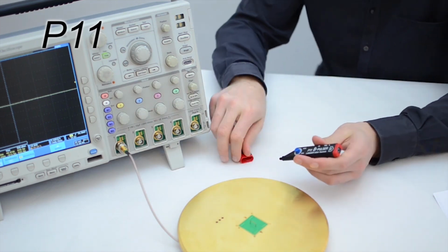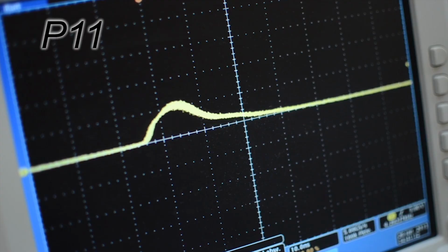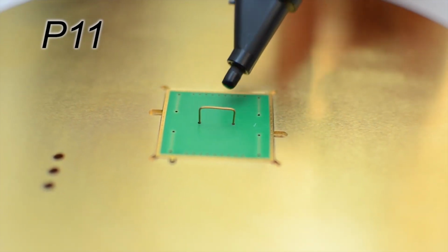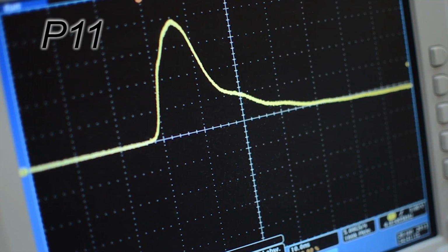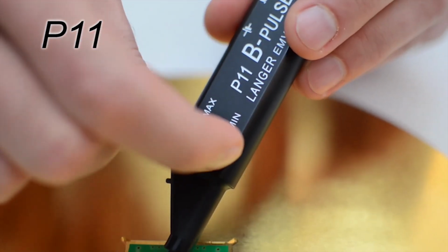The disturbance pulse is triggered by pressing the Start push button, and we then move the mini-burst generator towards the electronics. This is what the voltage induced by the mini-burst generator looks like. It has a width of approximately 5 nanoseconds and an intensity of 15 volt, perfect to interfere with an IC. We can modify its properties either by changing the distance or by turning the blue control dial.